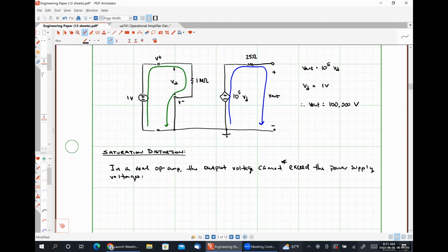Okay. Now there are certain types of op amp circuits where there is a little amount of dead space between the maximum output voltage and the positive supply voltage, and the minimum output voltage and the negative supply voltage, meaning that the output can't quite get to VCC plus and it can't quite get as negative as VCC minus. For the intents and purposes of this class, we are going to act as if we're dealing with rail to rail op amps always, okay? Meaning that our output voltage will never be more positive than VCC plus, and never more negative than VCC minus.